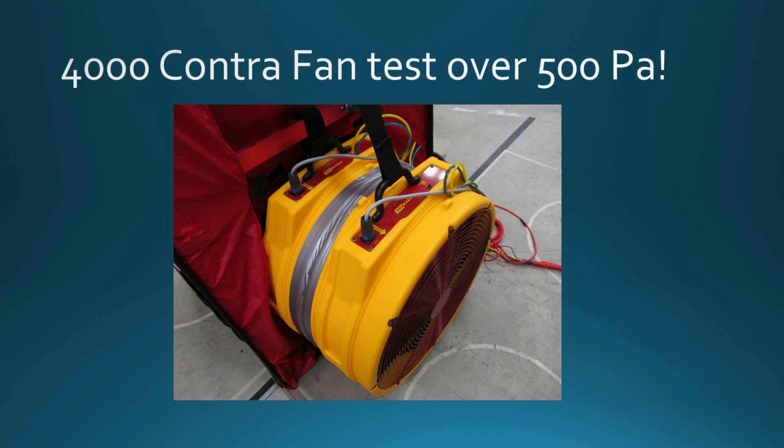So there is a faster way of doing this. I've done plastic on the ceiling 3 times, and I've done this method, which is called the BCLA, below ceiling leakage area test. And all we do is we run 2 fans. We duct 1 fan to the ceiling, and the new gauges that we have have what we call a set to 0 function. So we set the pressure across the ceiling to 0, and this fan, the one that's on top, will now measure the below ceiling leakage area directly.